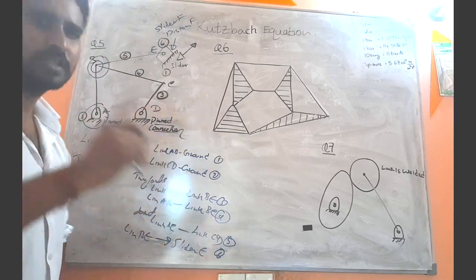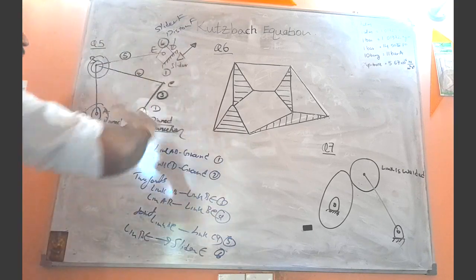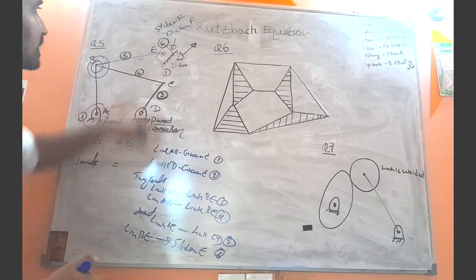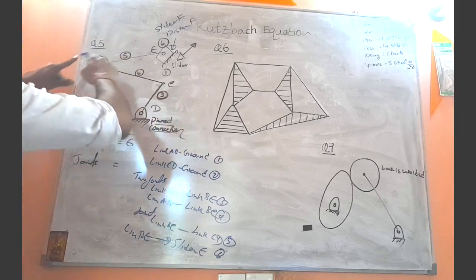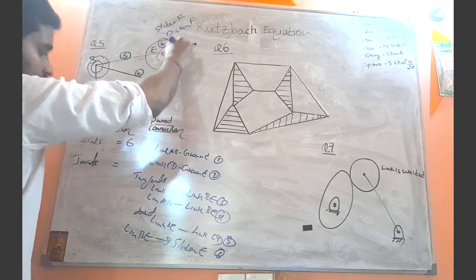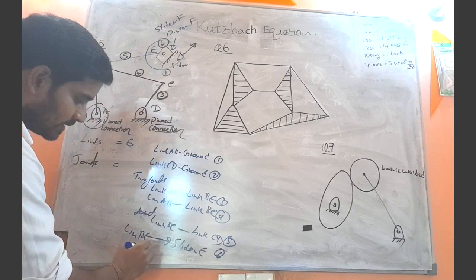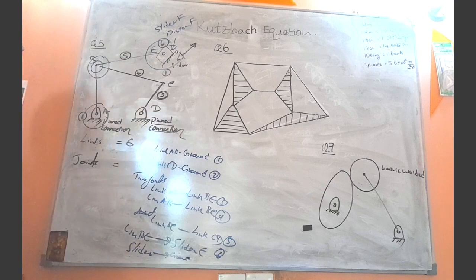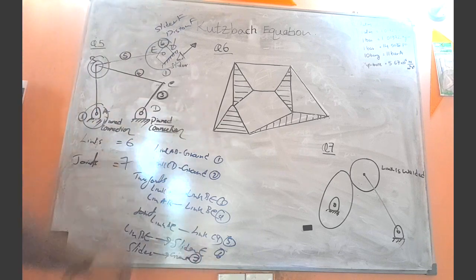That is the connection, the joint that connects the slider or the piston to the ground. So that means here also we have two joints. One joint connects the link BE to the slider. What is the other one? It is the joint that connects the slider to the ground. So 7. How many joints do we have? We have 7 joints. I hope now you got the point.